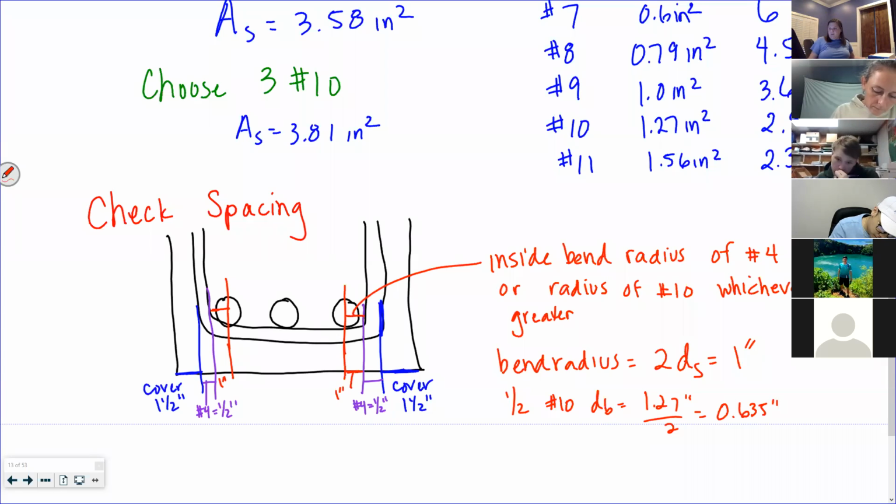And that's just saying we want the longitudinal reinforcement flat on the bottom, not somewhere up here, like nestled in. We want them all flat on the bottom in one line, because the one in the middle will be on that horizontal bottom. Do they touch the stirrup? Are they laying on the stirrup? Yeah, they're laying on the stirrup.